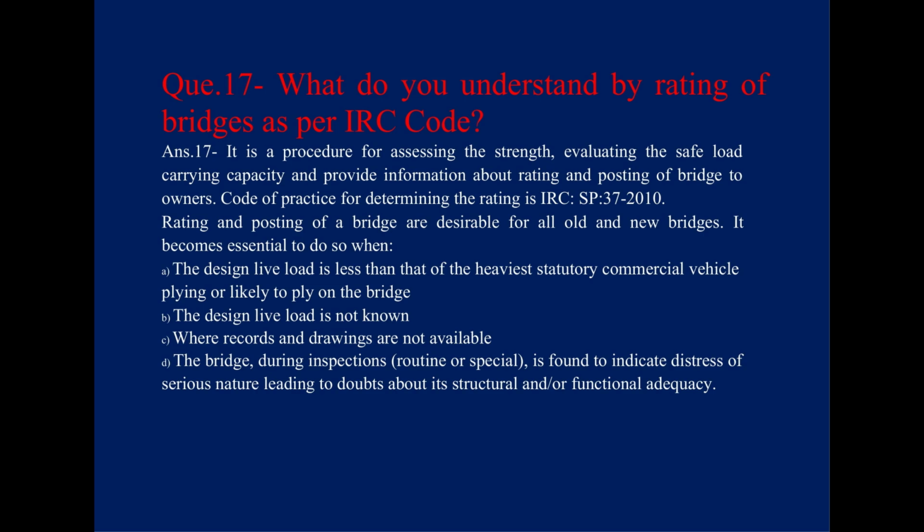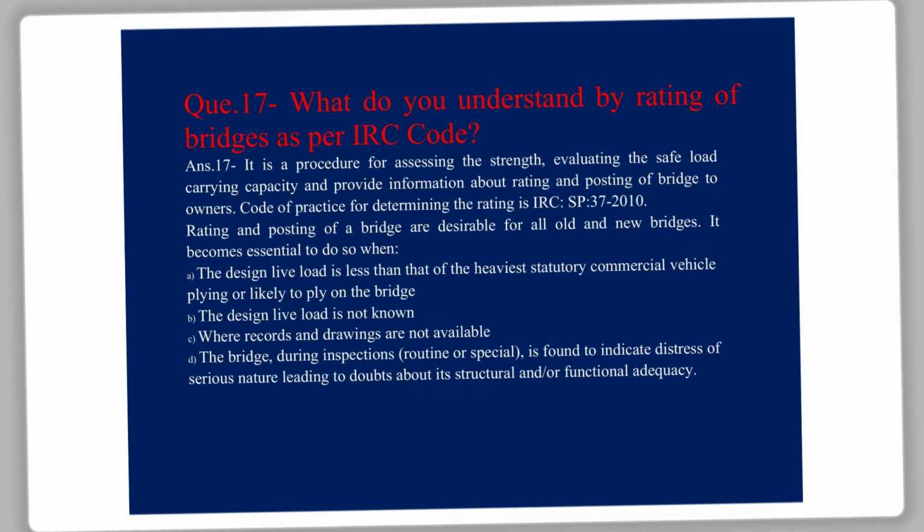It becomes essential to do so when: A. The design live load is less than that of the heaviest statutory commercial vehicle plying or likely to ply on the bridge. B. The design live load is not known. C. Where records and drawings are not available. D. The bridge, during inspections, routine or special, is found to indicate distress of serious nature leading to doubts about its structural and/or functional adequacy.